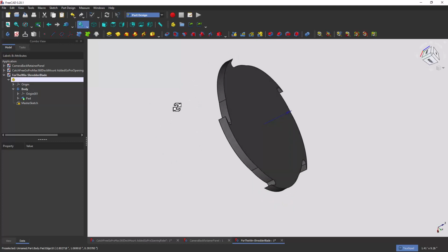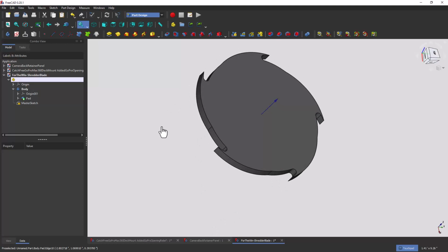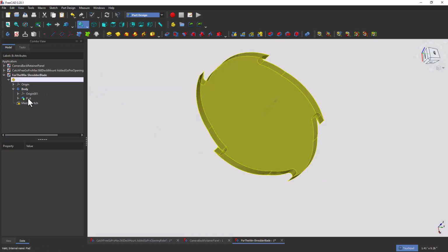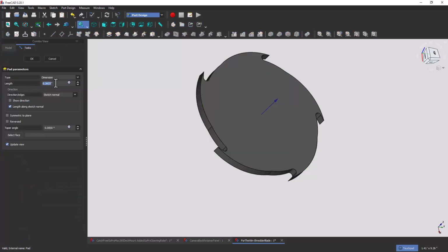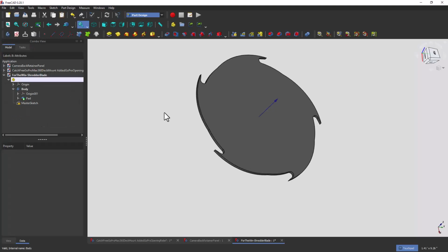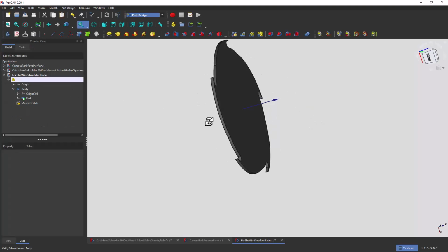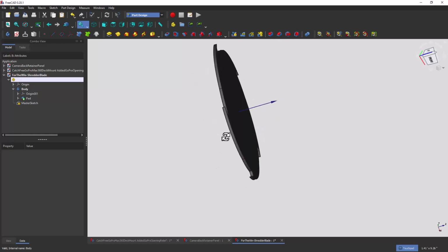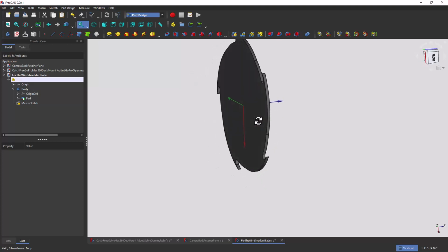That's the end of it, but it's not the end of it. If you were really going to design it, you'd start putting bevels and chamfers and different things on edges here. You wouldn't make it this thick, right? You'd figure out it's probably 1/8 of an inch. So if I go in here and edit this to be 1/8 of an inch thick, 0.125, okay, something more reasonable for a blade like that. You could technically get this thing to work.